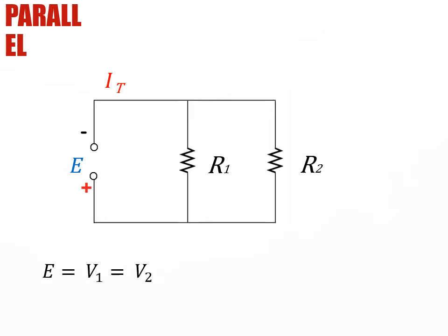So the voltage goes to the top of R1 without going through any other loads or resistances that will use up any voltage. And the top of E, the negative side of the voltage source, also goes to the top of R2 without going through any other resistances to eat up some of the voltage.